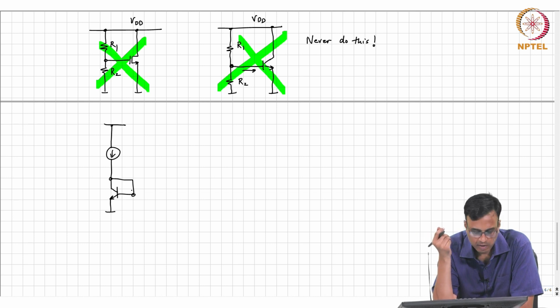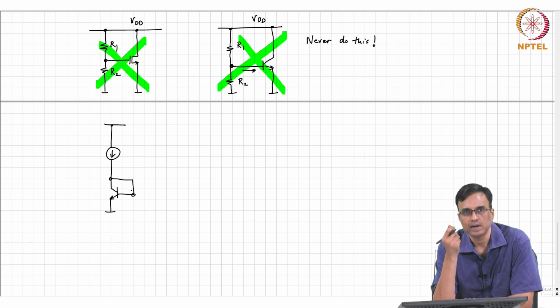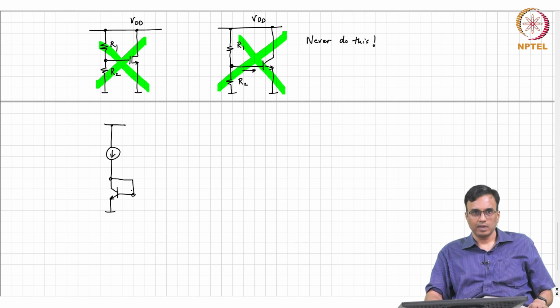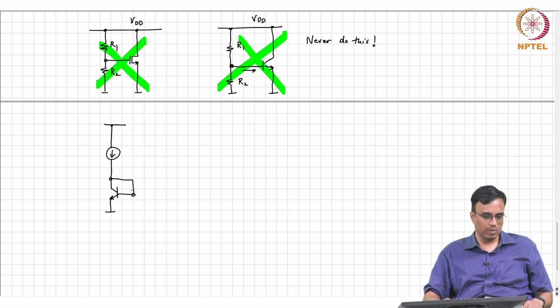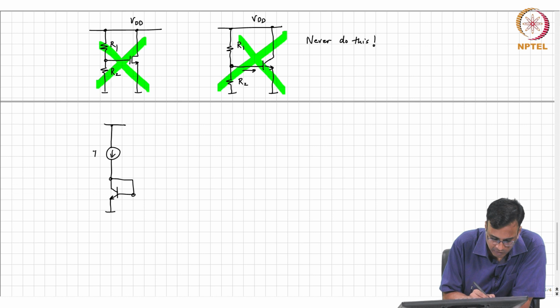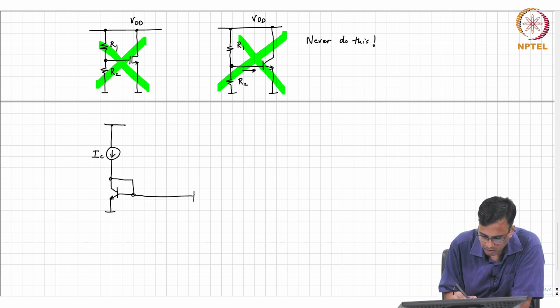Okay. So, you can measure the quiescent current of the transistor in two different ways, and you can adjust the base emitter voltage in two different ways. You can either keep the base fixed and vary the emitter voltage, or keep the emitter fixed and vary the base voltage, and that is basically what causes the feedback action to occur. So, you can think of at least 4 ways in which you can stabilize the bias of the bipolar transistor, just like we did in the MOS case, right. All these circuits are pretty much the same, so there is no point in beating a dead horse. Let me quickly only point out the differences.